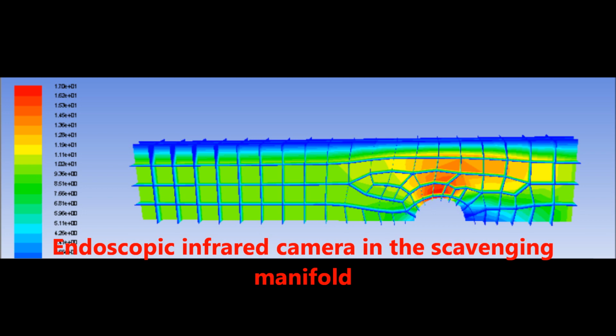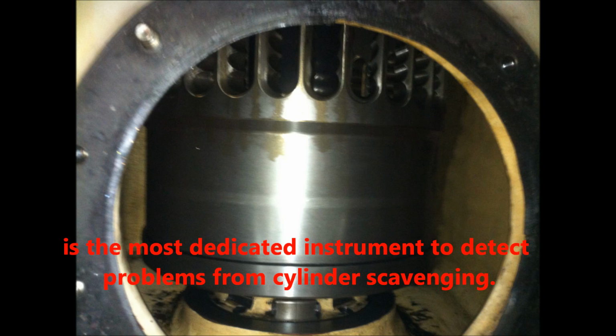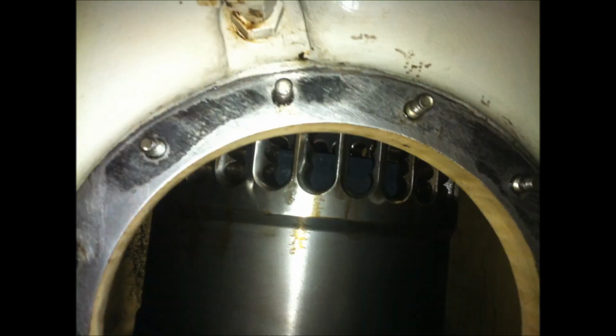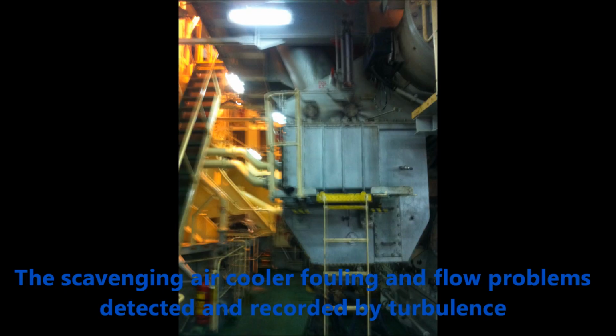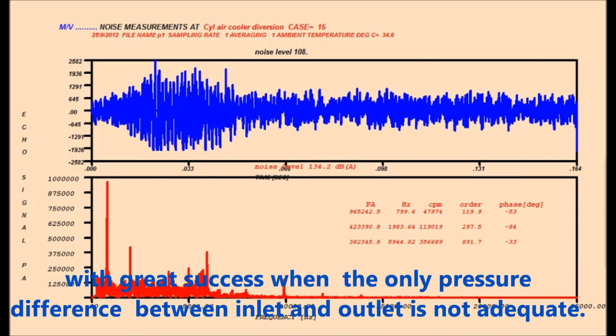An endoscopic infrared camera in the scavenging manifold is the most dedicated instrument to detect problems from cylinder scavenging. Scavenging air cooler fouling and flow problems are detected and recorded by turbulence detectors with great success, when the pressure difference between inlet and outlet alone is not adequate.